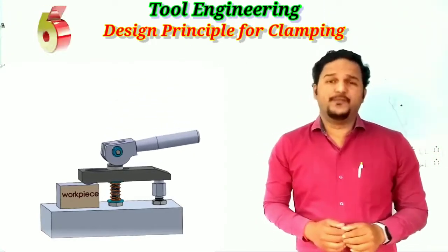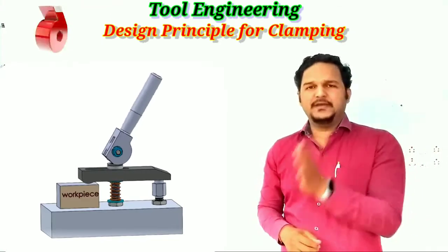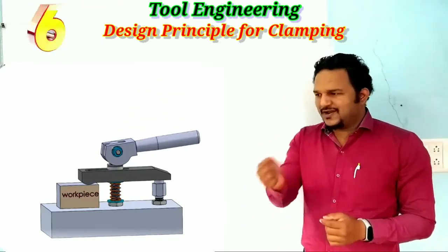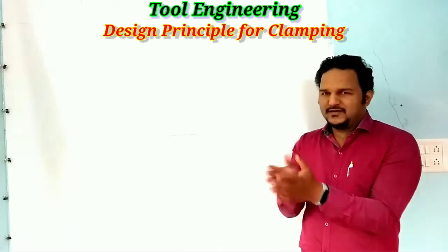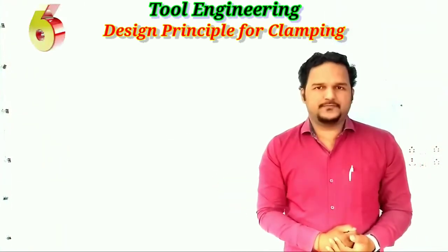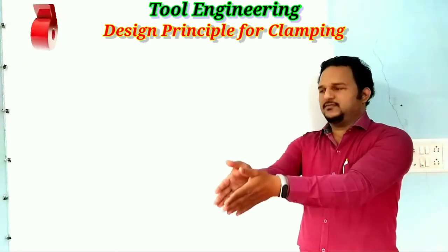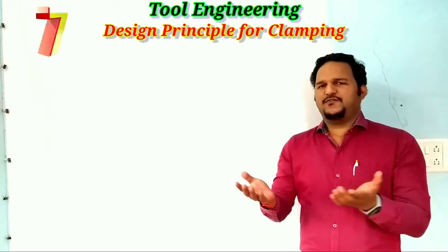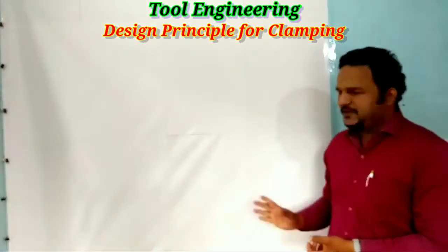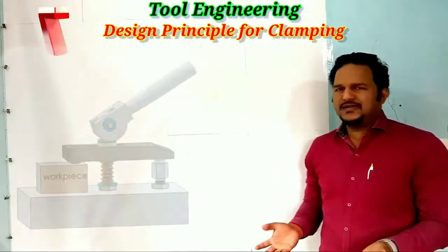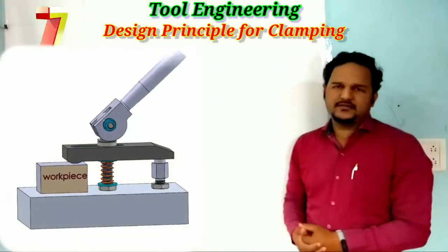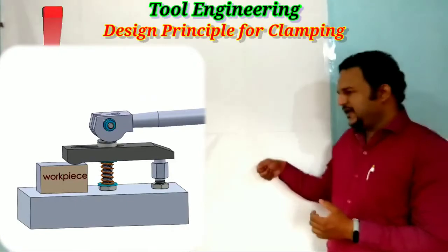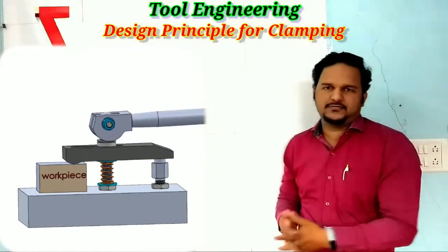Sixth point, the movement of clamps should be strictly limited, and if possible, it should be positively guided, so that when you clamp, it does not get away from the direction of clamping. Next point, whenever possible, lifting of the clamp by hand should be avoided. If it can be done by means of a spring fitted in it, we don't have to move it by hand. So the spring should do the work.